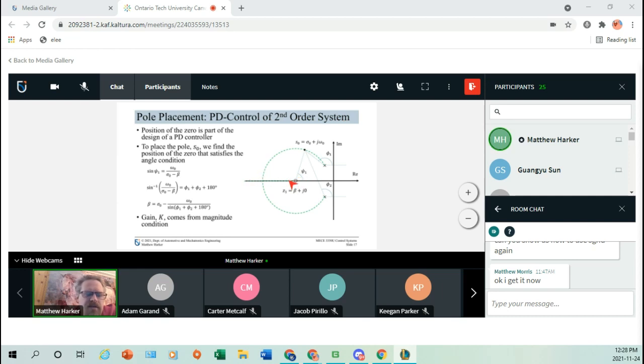So adjusting TD is essentially going to change the position of the zero and basically then move that locus around, right? So when it was off at infinity, our locus basically went vertically in this direction, and then it kind of wrapped around as we moved the pole in. Just that rough description there.